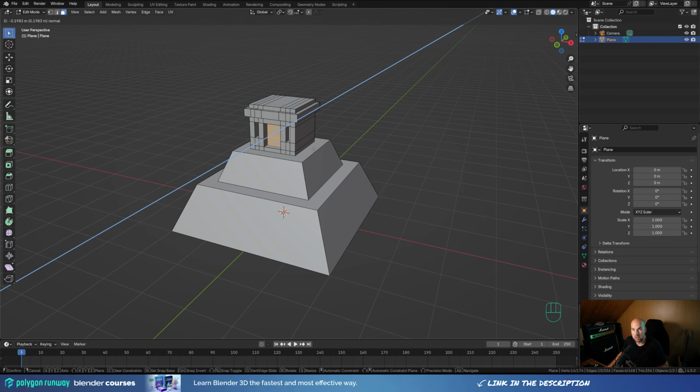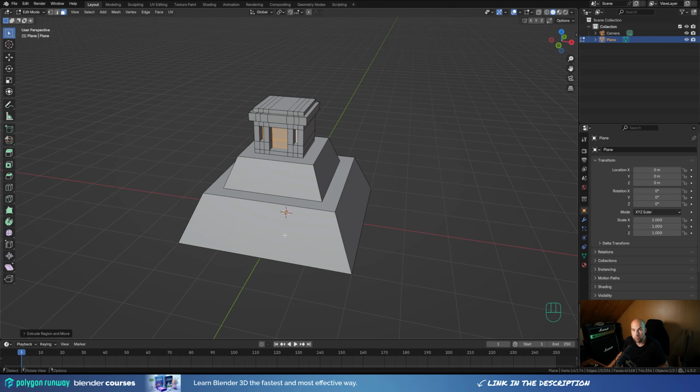You don't need to go too deep because we'll color them with black color anyway, so let's leave it like this for now. And now we'll create these stairs, and to maintain that slope we can reuse some of the geometry. So let's select this face right here, press Shift D to duplicate, right click to release in place, and then press P and separate the selection.